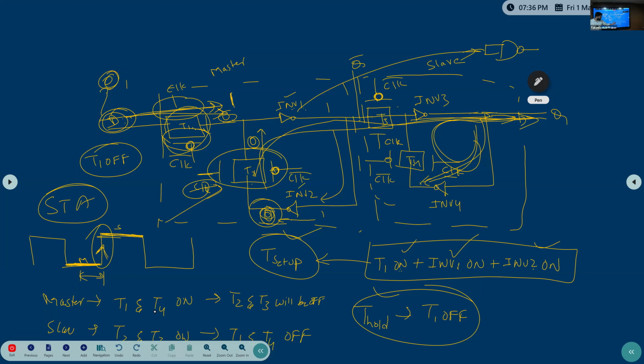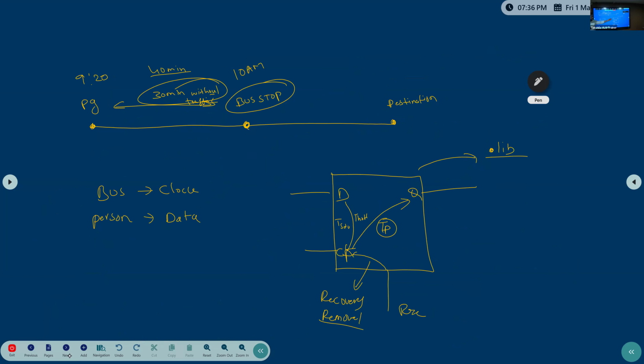If you know the setup time and hold time, if you meet the setup time and you meet the hold time, then the flop properly operates and it will store the data properly and send the data to output Q properly. Yes or no? So whatever the data setup time, how the timing is going and how it is reaching Q, if I represent it in the arc format, those are these timing arcs.